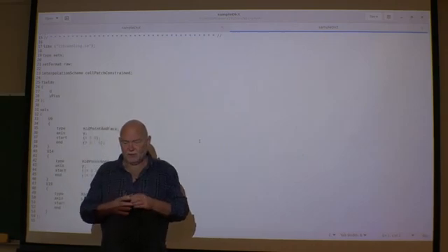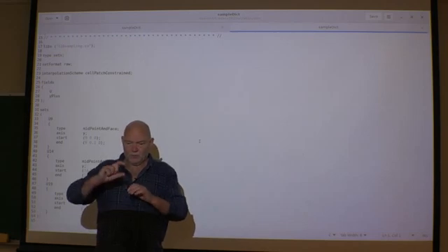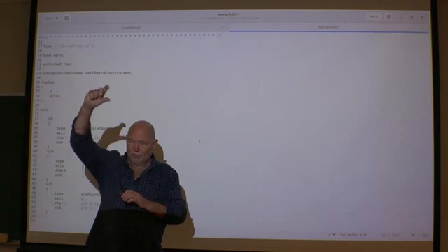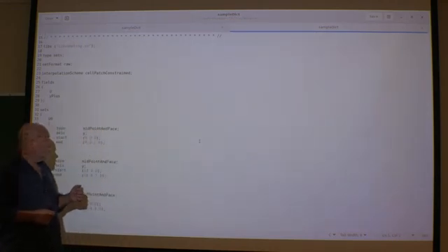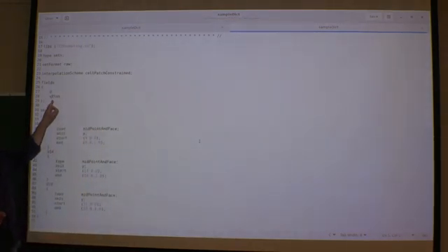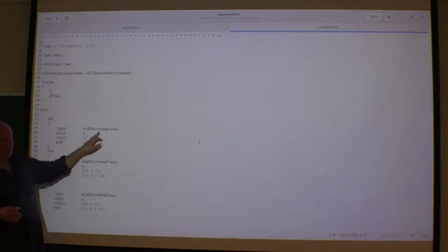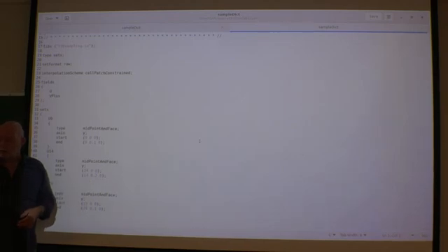For the velocity it is a little bit weird because you will have 2 constant values and they operate in pairs, so it looks a little bit strange. I didn't really need it, but I had to do that one to get my y plus at this x location, because it's only calculated on the cell faces. If you only want the velocity and nothing more, then you could use midpoint and nothing more. Then you will only get the cell center values at that location, no average, nothing. So there you have a recipe.